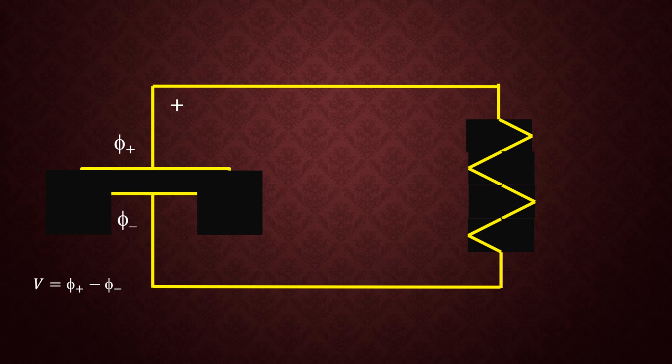Okay? Now, if we go along the circuit, we have a section of, in effect, zero resistance, namely the top horizontal part. So that if I were to measure the potential, since this resistance is zero, the potential is the same as I go along that section of conductor. Similarly, the potential is the same along that lower conductor. So the fact that there is wire connecting the source and the resistor, and as long as the wire has a very low resistance, then the potential is the same throughout that region.